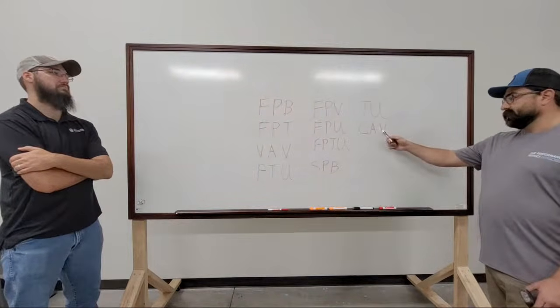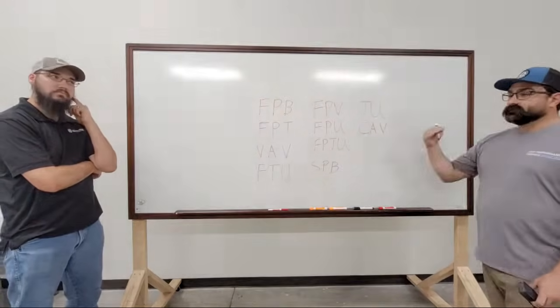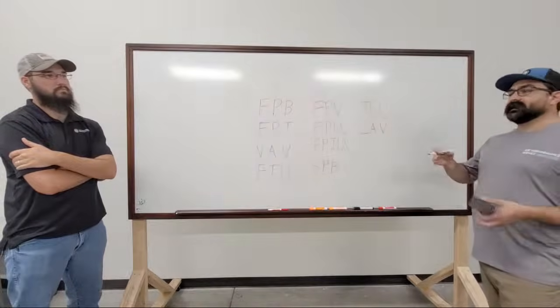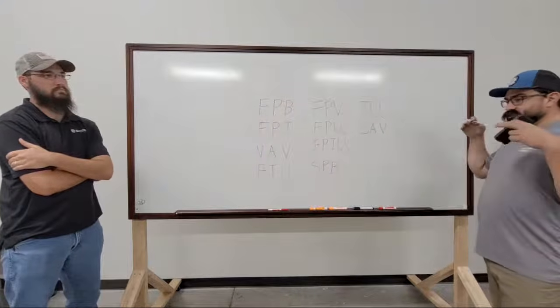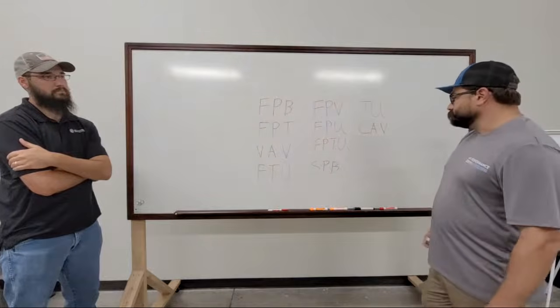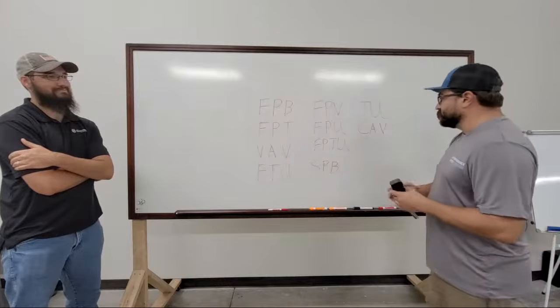Or that could be like an exhaust VAV or an outside air VAV. It maintains just a single set point, doesn't care what the temperature of anything is. It's not even looking at a thermostat, it's just maintaining flow. Yeah, so there's all our fun random nomenclatures.